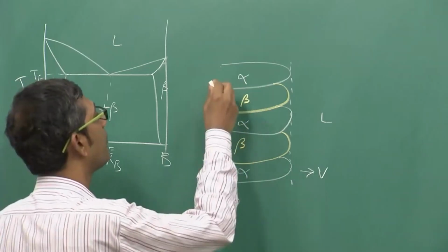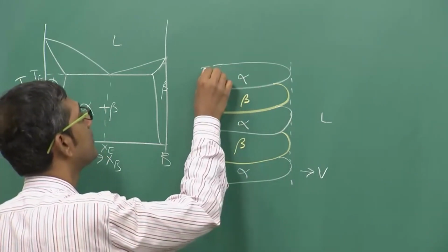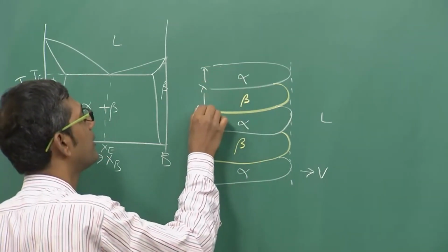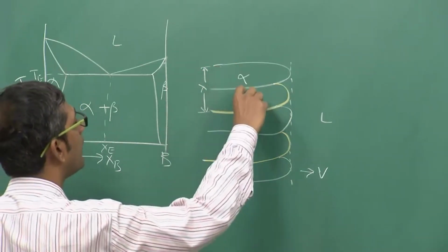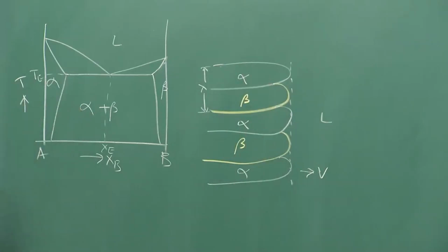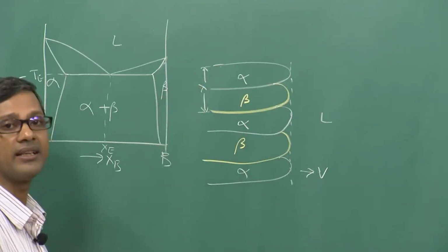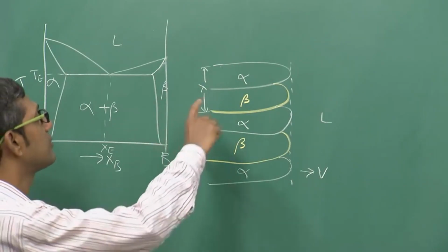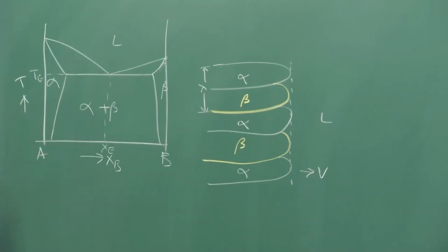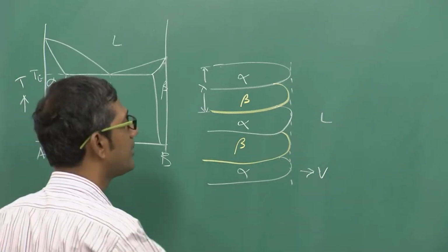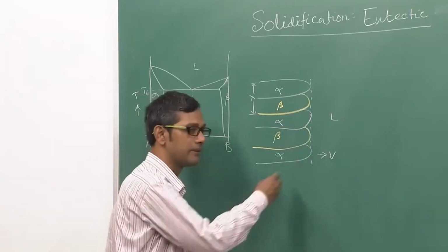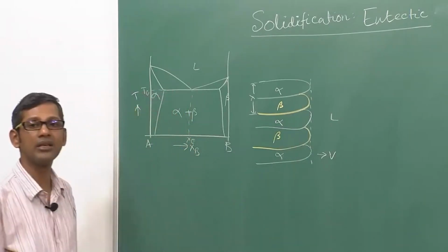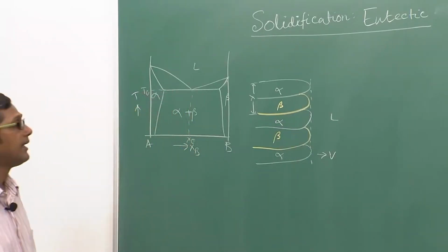As you see, this is lamellar, so therefore interlamellar spacing, the way we define it also in the book, is like this. This is the lambda, the thickness of the two lamellae, one is alpha, the other one is beta, and this is the most important microstructural characteristic which is used to determine the important mathematical equations. Obviously this growth is basically possible because of the undercooling of the liquid. As you know, if the liquid is undercooled, then only any phase will grow.